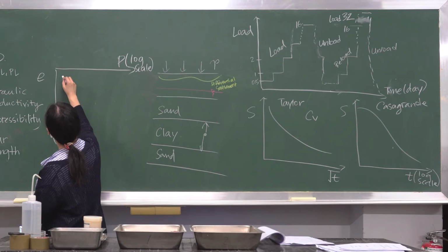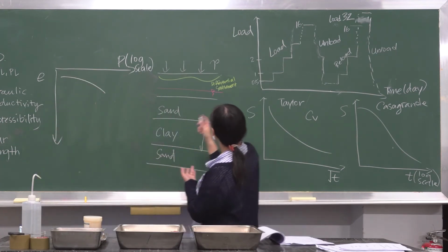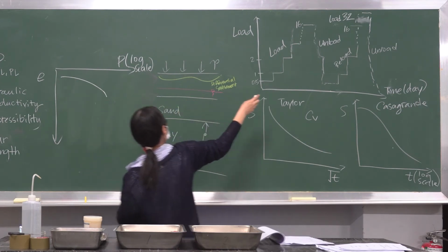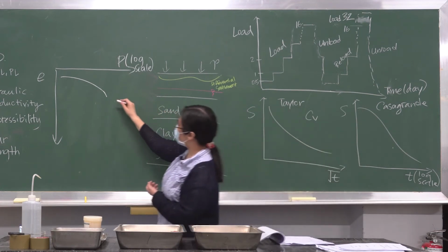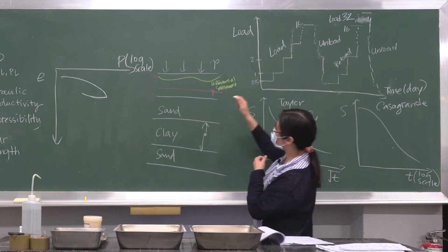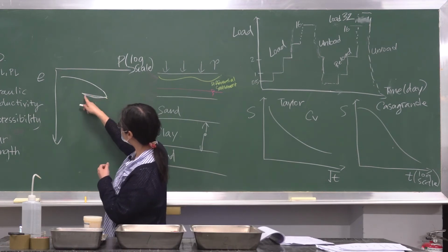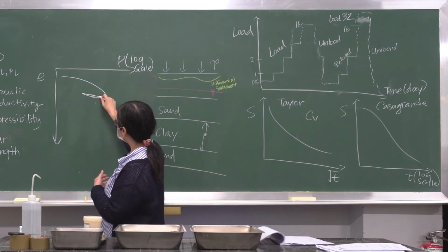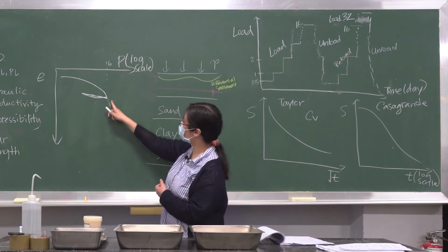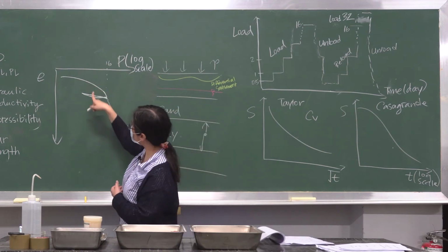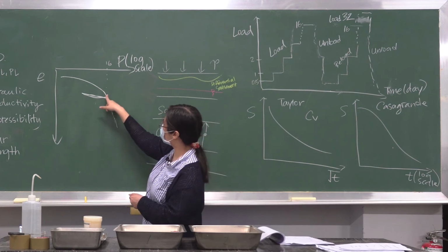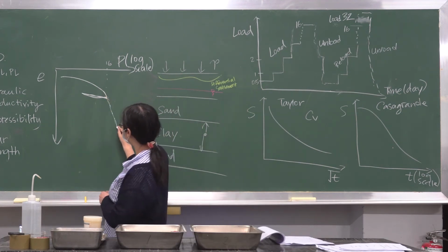What you expect to see is for the first loading stage from 0.5 to 16, you will have this curve here. And then when you unload from 16 to 0.5, you will have this unload curve. And then when you reload again from 0.5 to 32, basically the curve would approximately look like this. Once it reaches 16, it will continue with what you have previously. So this is the loading stage, unload and reload, and after it hits 16 kilogram, it will continue with the previous curve again. And then lastly, you will have to unload.